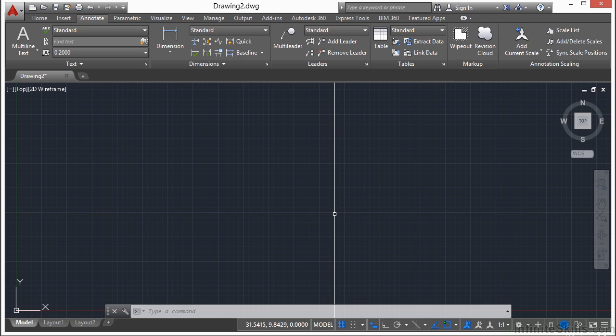Now, as I stated earlier, there are different ways to use text in multi-lines, and you need to let your styles control your font type. MText objects can be edited within the text editor, but once you do, you lose some of these controls or abilities. For example, let's load in some text, and I'll show you a trick on how to load some text.